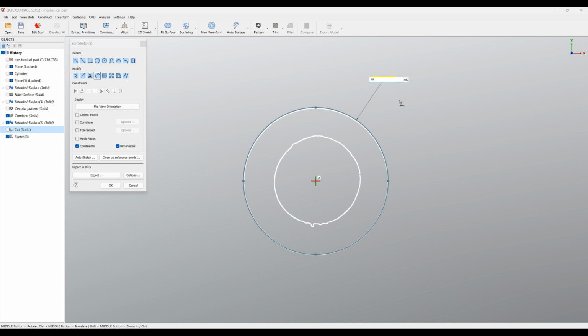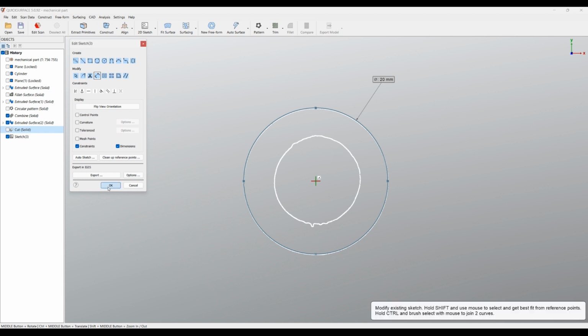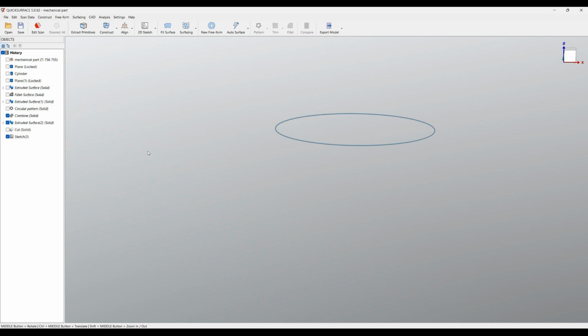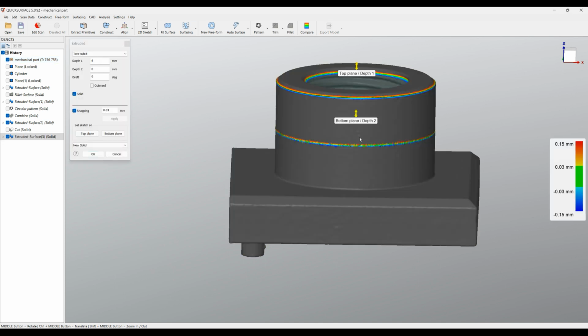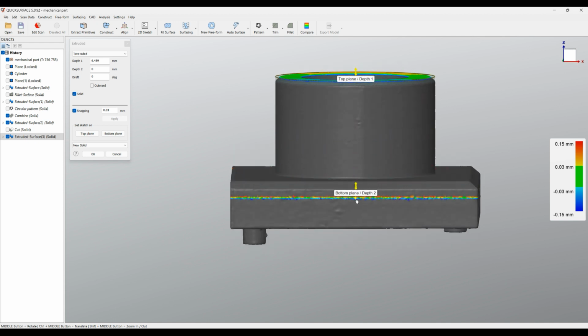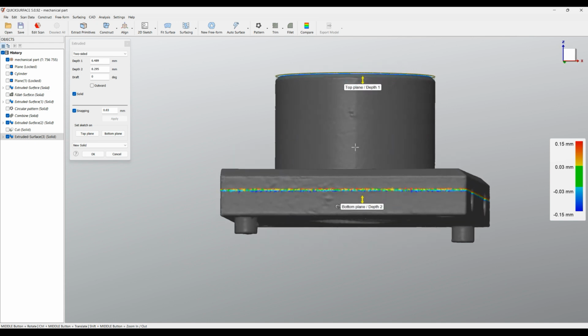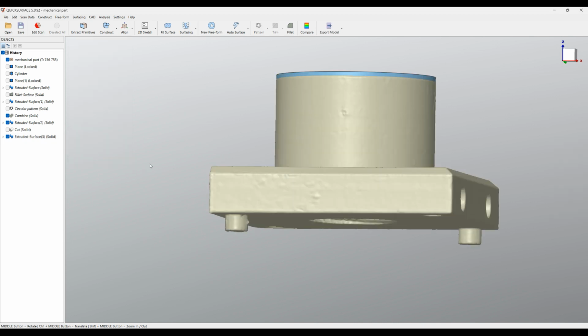Now this is the design intent. It's really up to you to decide what you want to do, whether you want to follow exactly the shape or you want to provide something that is fully manufacturable. Let's see what we did. I'll just show my part, click on it and create my extrusion. Because the snapping is turned on, I'll just drag it on top to pick a good location. While for the bottom plane, I will just drag so it goes inside our body and press OK.